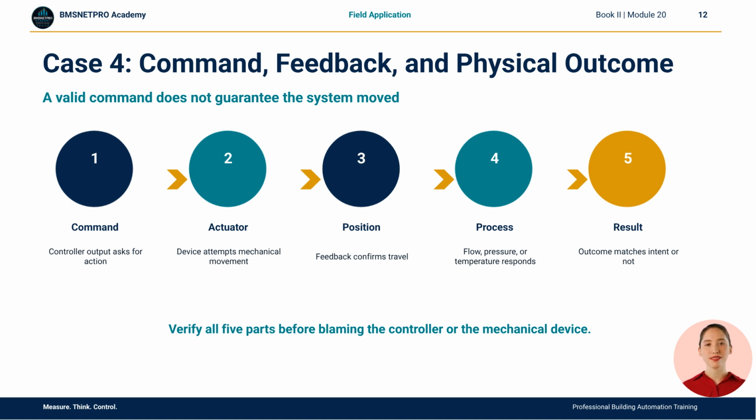The workbook asks the learner to verify each link. Is the command correct? Is the actuator receiving it? Did the device move? Did the process respond? Did the outcome match the intent? This protects us from replacing controllers when the issue is linkage, or replacing valves when the issue is a measurement assumption.